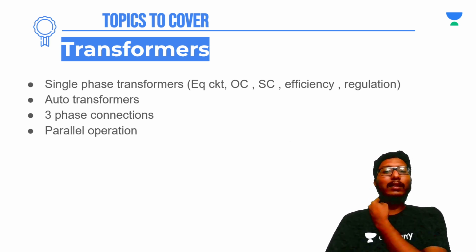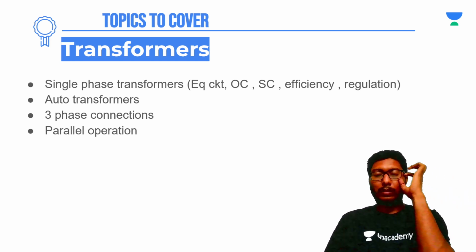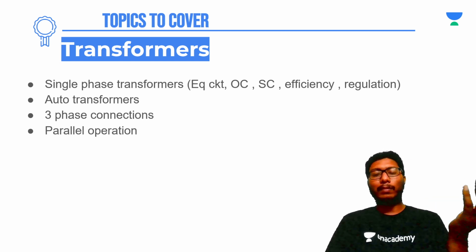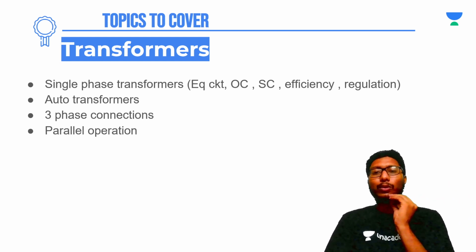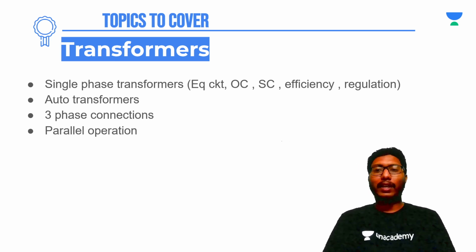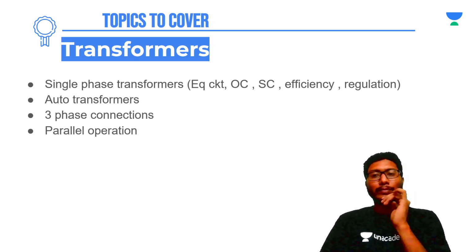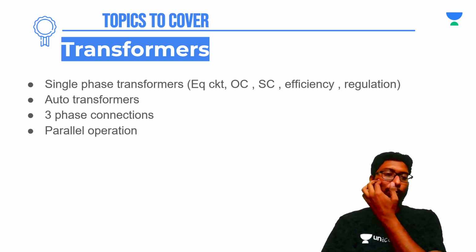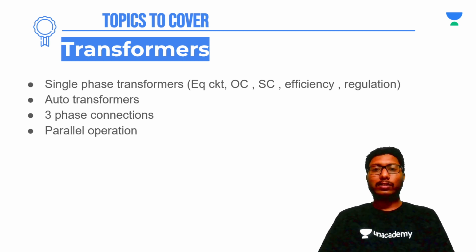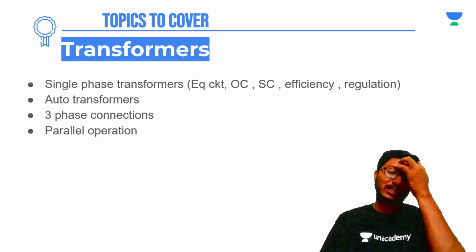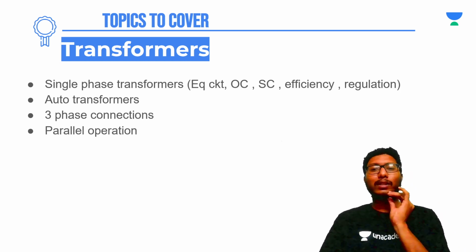And also there are different conditions for maximum regulation and minimum regulation. So what these conditions are, you should know, and how to calculate this voltage regulation exactly and approximately. And in the examination you should not be using the approximate formula, you should be using only the exact formula, because in the GATE examination recently they are testing these approximations, that is where the chances of committing a mistake are more, and those things are being tested. So you should be using the exact formula, that is involving the whole square of I naught square r square cos square phi plus I naught square x square sin square phi by v square, power 1 by 2, that you should do.